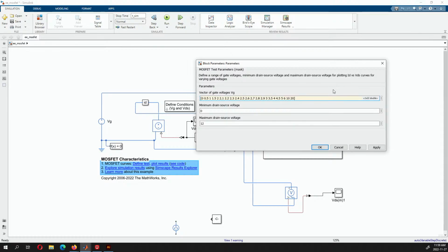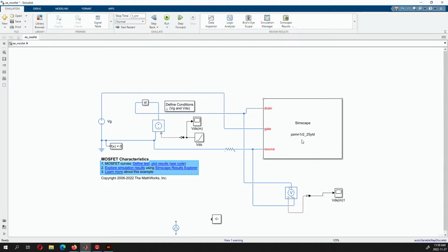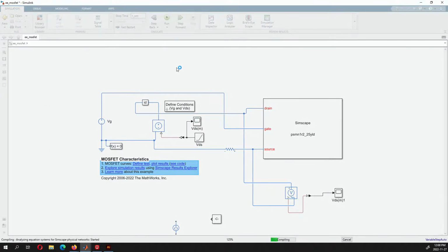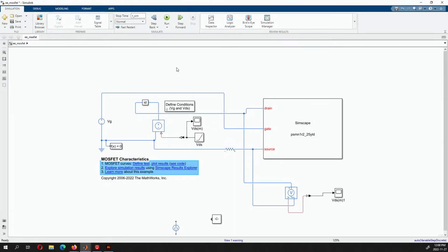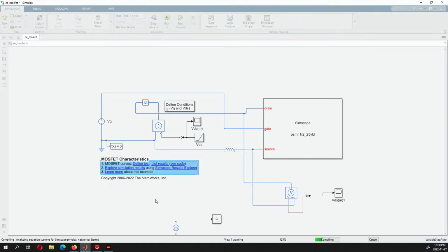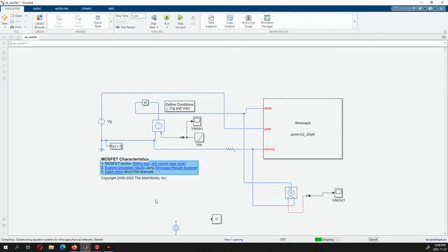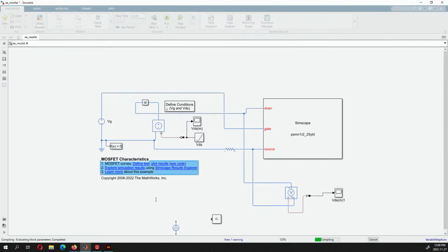So this tells me, when I am creating my ESC, my electronic speed controller, at what voltage I should be applying to the gate of this MOSFET so that I can minimize resistance when it's switching. That's what we're really getting at over here. And we're switching 6 MOSFETs to control a simple brushless DC motor. And you really want it to be conducting and having less power dissipation or losses.